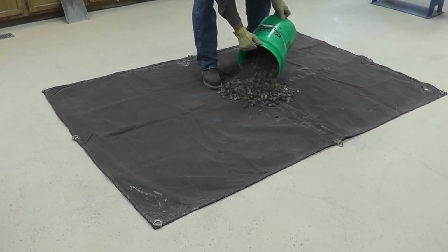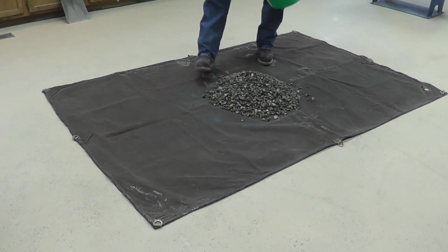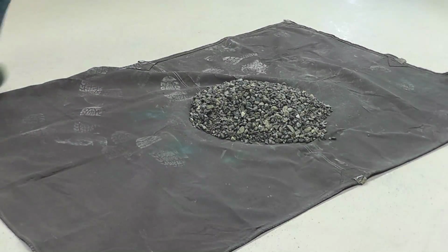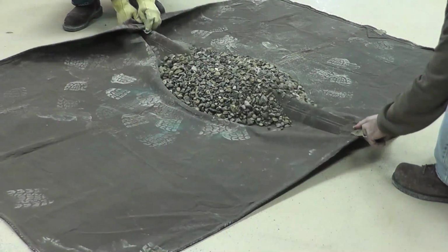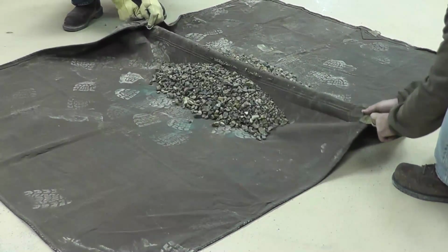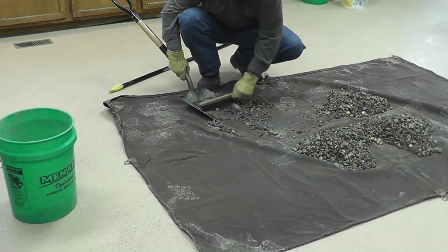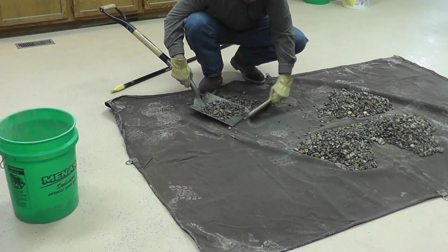Now let's have a look at Method B, quartering. In this method, a sample is placed onto a surface, mixed, and then shaped into a conical pile. A splitting device is then used to quarter the sample. Subsamples are removed from two opposing quadrants of the quartered sample and combined to represent the first split. Further quartering may be required.